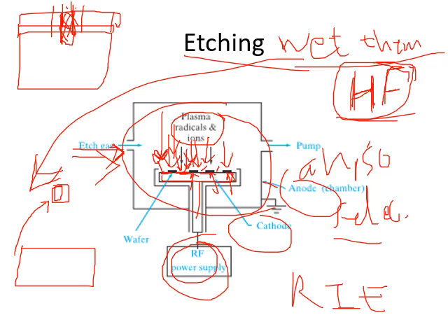Dry etching is done nowadays, but earlier we had wet etching, right? In wet etching, the problem was with the isotropic nature of that wet etching material, that is HF, right? But in dry etching we have anisotropic property and selectivity property. Both the properties are satisfied.